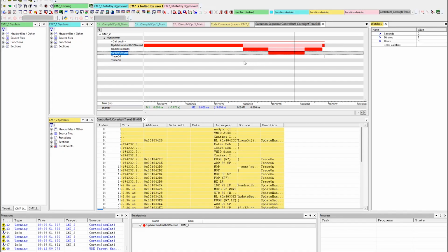That's because we have only a limited amount of trace memory available. And to do a more detailed timing analysis or something like that, it makes sense to switch to the external trace interface and store the trace information into the UDE device. For example, in our UDE Next, we have up to 512 megabytes available. And as I told you before, to use the external trace memory, we have to configure the pins that are shared with the GPIO so that they are used for tracing.